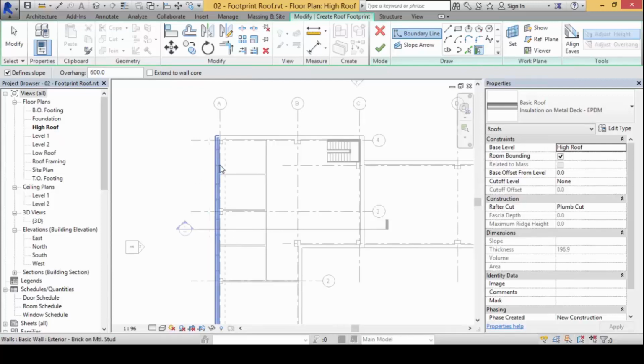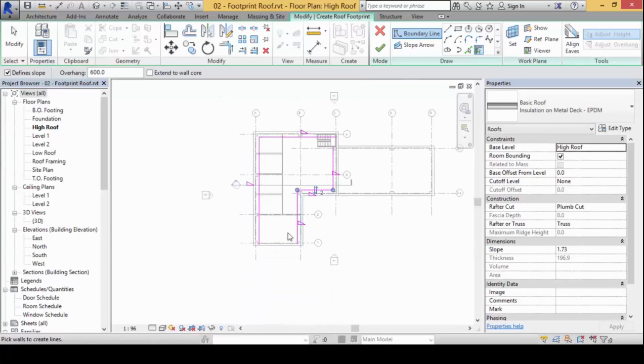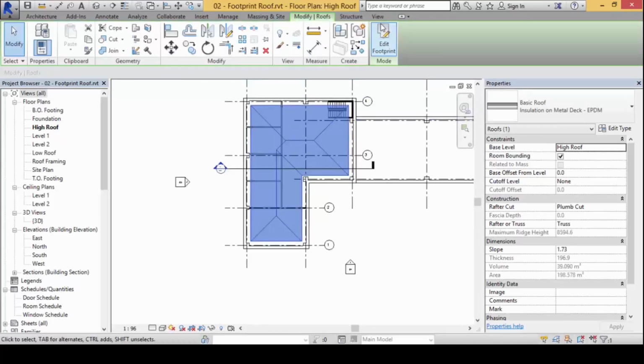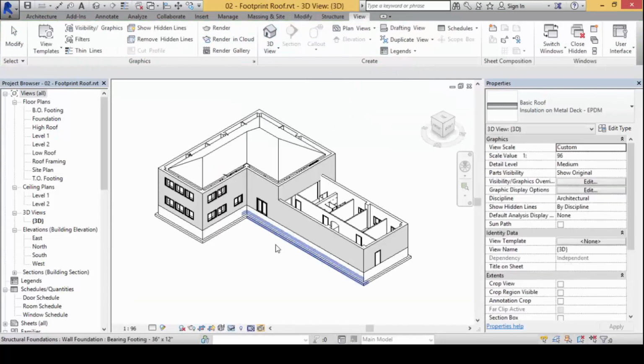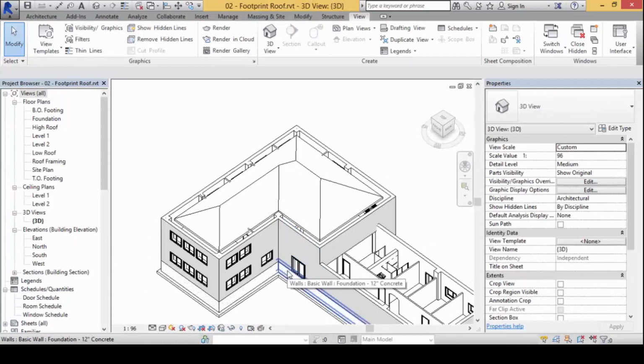Now what happens is, Revit will show you the outcome in hidden line right here, whichever side you overhang. Now I don't think we want to overhang inside this way. What's going to happen is, if I overhang this way, I'm going to show you one comical example. I'll overhang it this way, like this, and I'll mop the floors up, and I'm done. Okay, guess what? Check this out. There you go. You might as well not have a roof, because it's going to drip and you're going to have a swimming pool inside the building. It's a bit of a problem here.